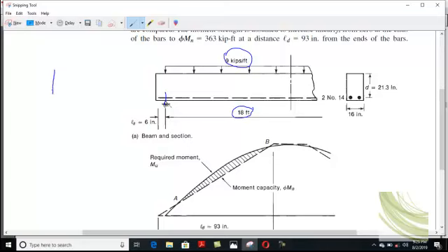And remember, whenever you are placing your simply supported beam on the support, this is your beam. They assume the moment diagram from this midpoint, so this is the zero moment point. And the bar is extended from this point towards the support side for a distance of 6 inches. That is the La distance.